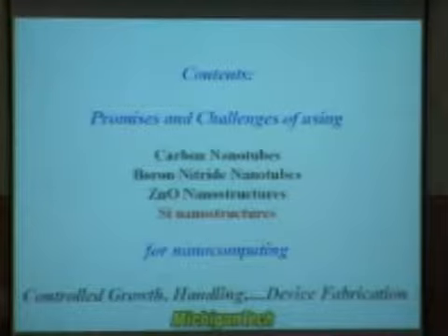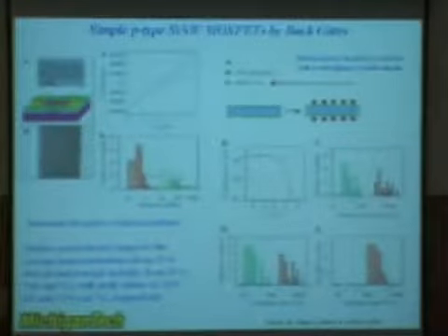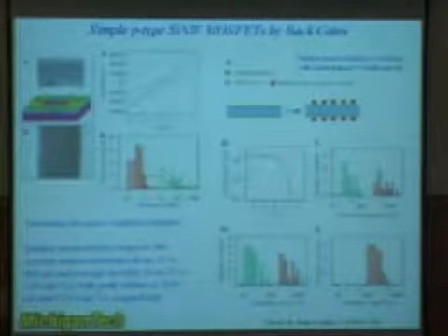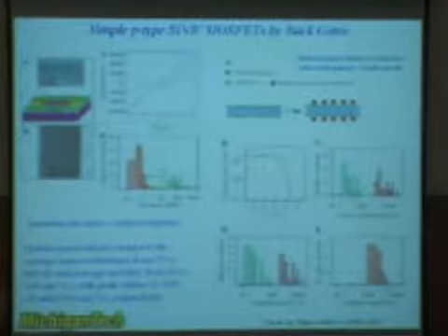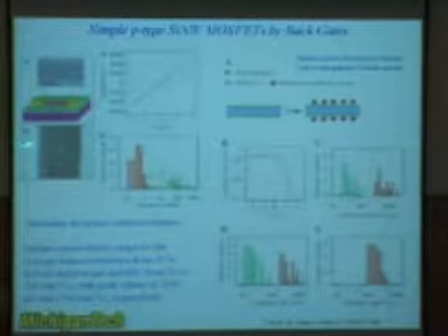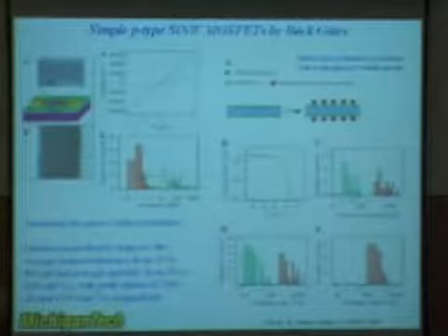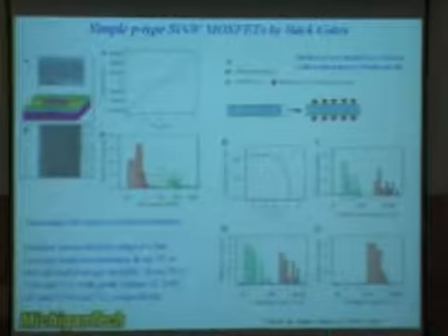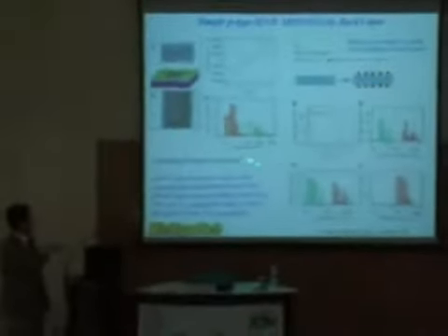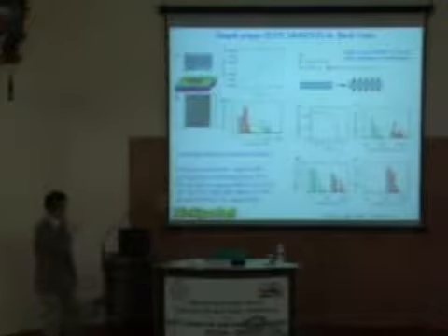So let's revisit the possibility of silicon nanostructures. We actually already have so-called silicon nanowires, right? It's just a one-dimensional silicon structure. And it can be grown at a diameter of 10, 15 nanometers. And actually, the device is already shown here, one piece of the wire across source and drain electrodes. And what was discovered by Harvard University in 2003 is that annealing will decrease the contact resistance between the wire and the electrodes.